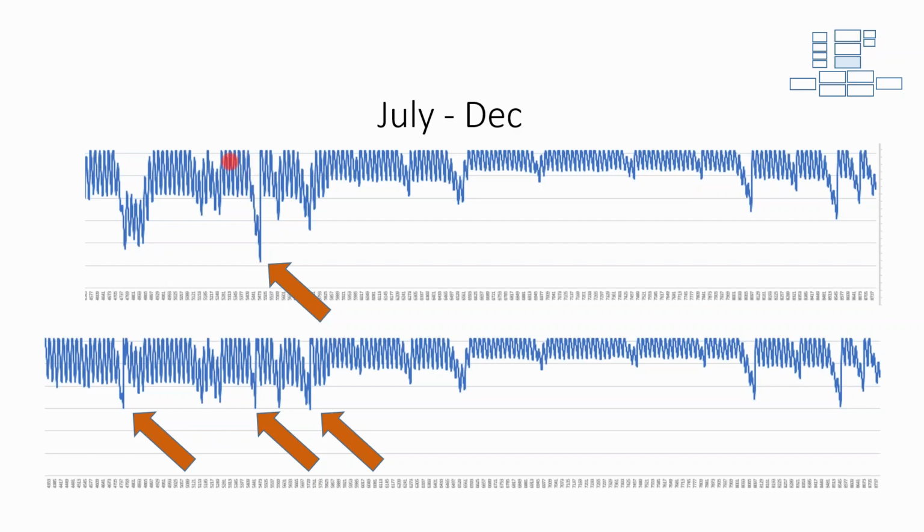As we said, okay, in this storm cycle in the summertime, in order to get to no more than an 80% depth of discharge, the top of this line here needed to be 122 kilowatt hours. And so that's how we got to 122. Now, in normal operation, because we have a generator on site, we're never going to get here.